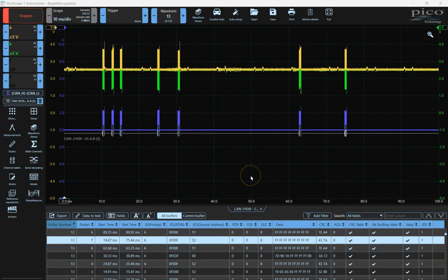And I looked through all of this data that I had for this machine, for these oscilloscope traces, and I did not have the DEF header communicate any time at all during that, whatever it was, 30 seconds or so that I'm connected to the CAN bus. And so this could be a message easily that is only broadcast, I don't know, maybe once every 30 seconds, maybe once a minute. It's the DEF fluid level, which we don't expect to change rapidly unless there's a big hole in the tank. But even so, if I got that information at once a minute, that's probably often enough.